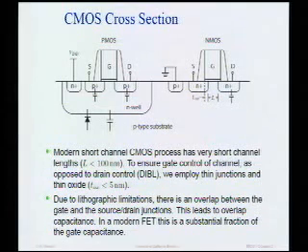What's also happened is as we've made these channel lengths smaller and smaller, though, our devices have become less and less ideal. By that I mean in an ideal FET, the gate has control over the channel. The gate is the boss, right? And the drain basically should not have an influence over the current once you're in saturation region, right?